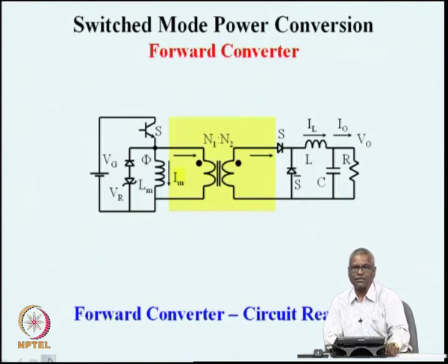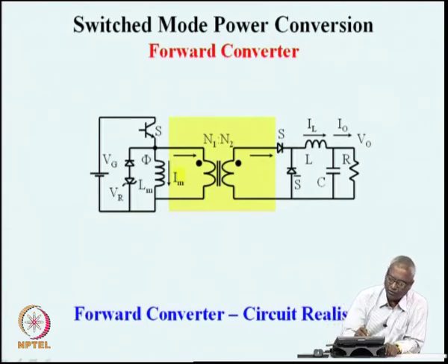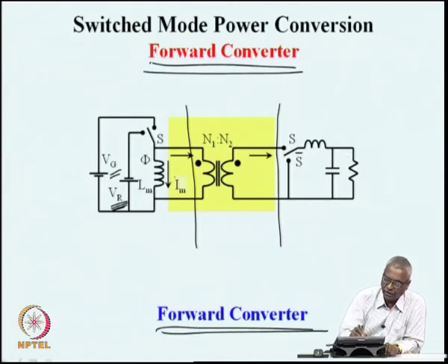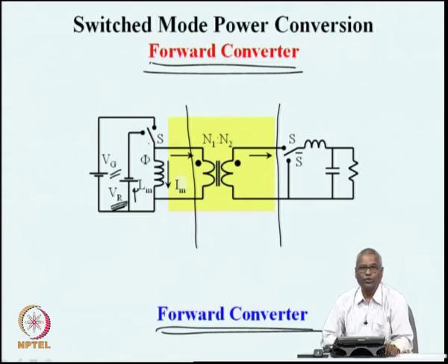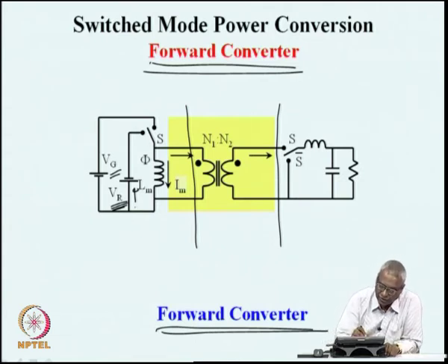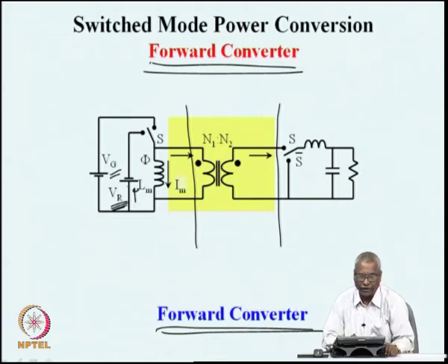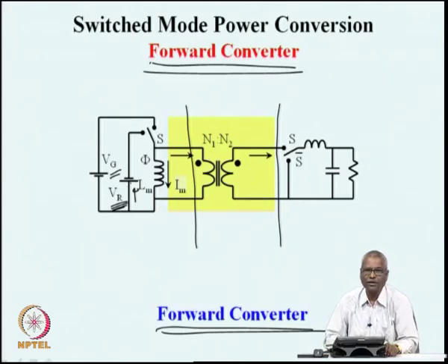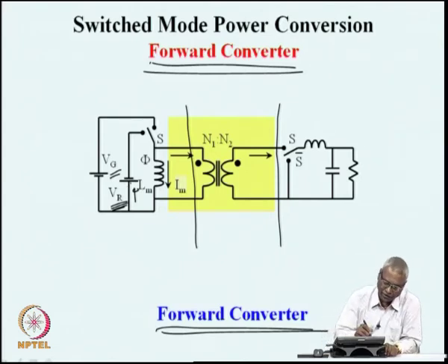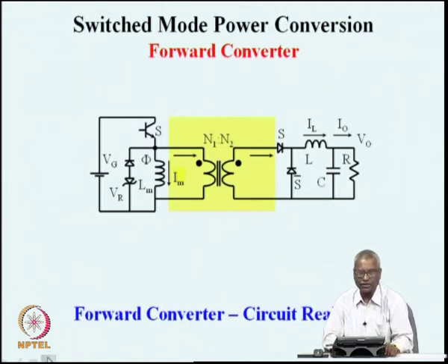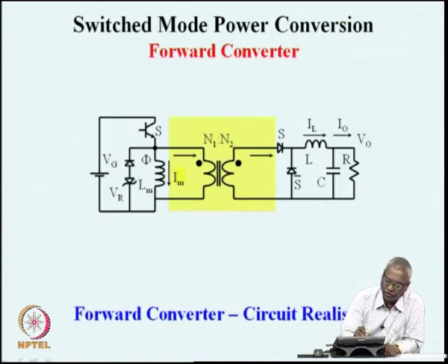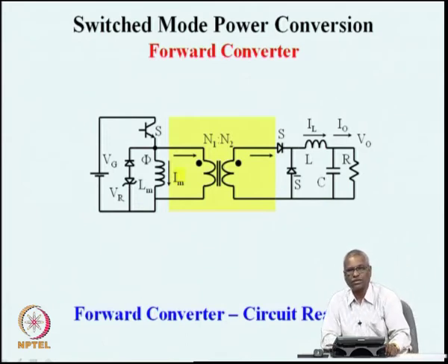Now, in the circuit realization, Vr is not provided by a source, because in the previous circuit that we had seen, the magnetizing energy eventually flows through this Vr during the time S is connected to the reset circuit. In such a case, power is being supplied into Vr, power is not being drawn out of Vr, it is dissipated in Vr. If that is the case, Vr can be a dissipating circuit element, and the way to realize this circuit is to connect to the transformer in parallel a circuit which has a constant voltage.